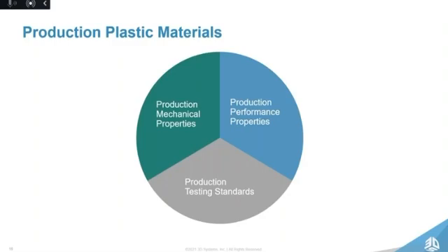So in order to ensure we can compete against traditional thermoplastics, which is really the basis of what we're talking about here, we've really strived to ensure that our material data sheets carry the most comprehensive data that's relevant to the envisaged application areas. Importantly for automotive, that's carrying out the reported and proven accelerated aging testing, both indoor and outdoor, showing retention of mechanical integrity with exposure to common fluids and chemicals, and showing mechanical isotropy.